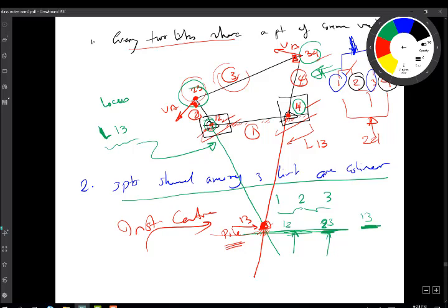What I can do is extend this line here, and I know this will be a locus for 2,4. Now I need to find another locus for 2,4. If I extend here, this is point 3,4 and point 2,3. The common number here is 3, so the missing point is 2,4. When I extend that, I get another locus for 2,4, and where they intersect is point 2,4.